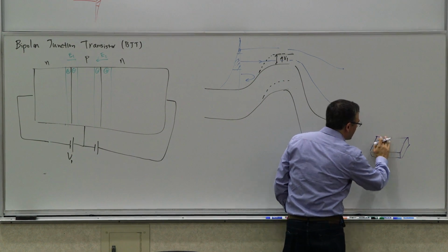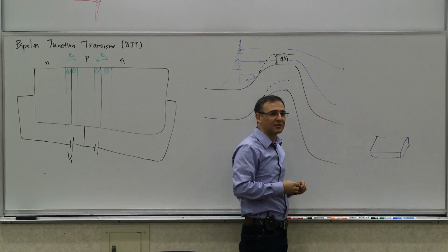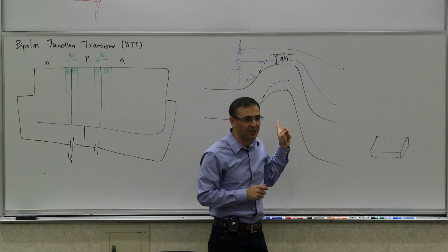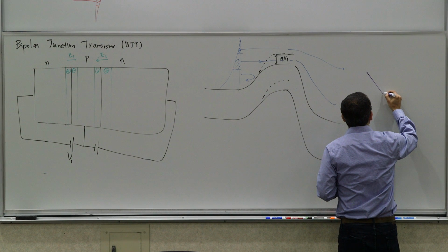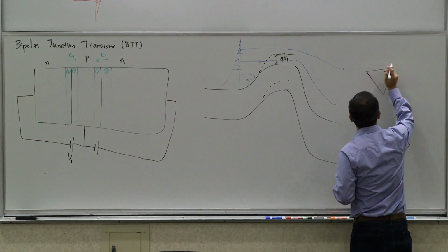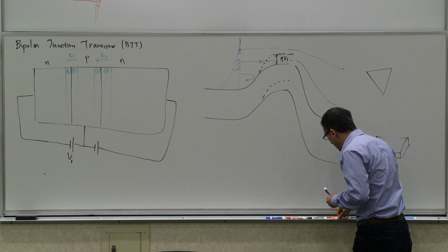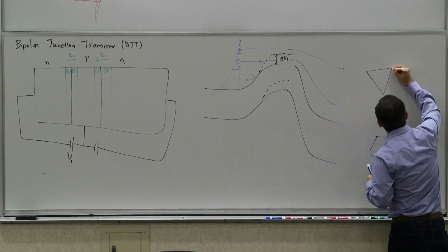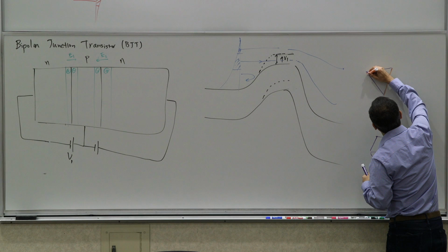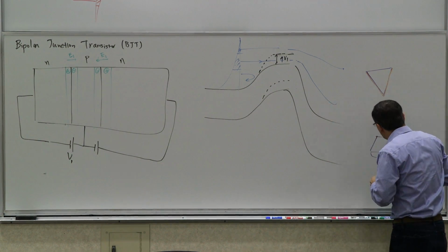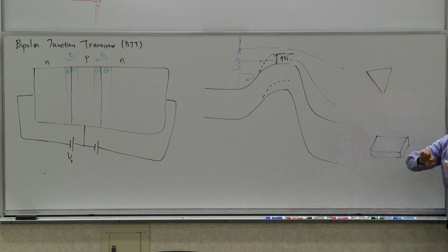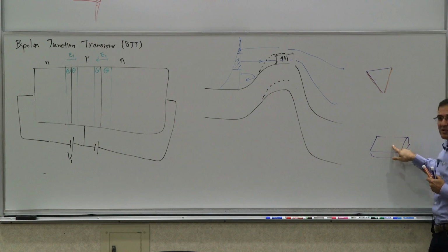But anyway, the interesting thing is that it was a point contact transistor. It was not a BJT. It was not this kind of transistor. One of the things about the way they made it is the following. So they made a little wedge of some non-conductive material. And then they had a coating of conductive material on it. And they were trying to make these 2 points pretty close to each other. So they made a little cut there. And then they mounted it on a substrate, on its semiconductor substrate.